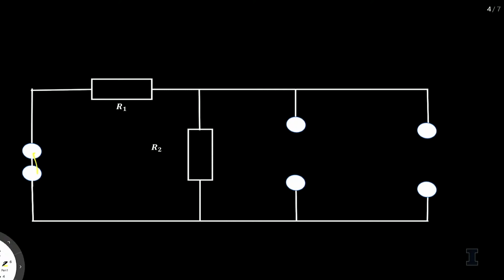So you want to remember that it's important when we take this perspective VAB and we're looking through our resistors that we're going to take this voltage source and this is always going to become a wire. On the other hand, when you have a current source, you'll note that it becomes an open circuit. And this is important because we're going to compare the circuit from these two different perspectives, again, always looking from the point VAB. So the first thing that we have to do is understand how the circuit is functioning through these two resistors with respect to our voltage source.